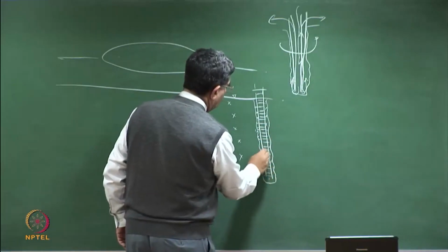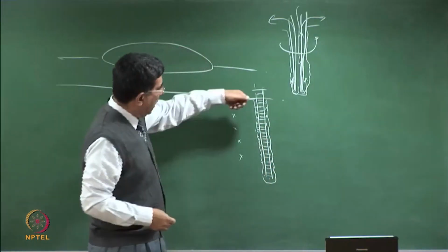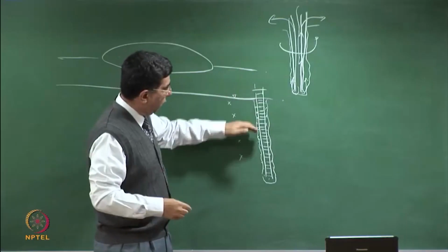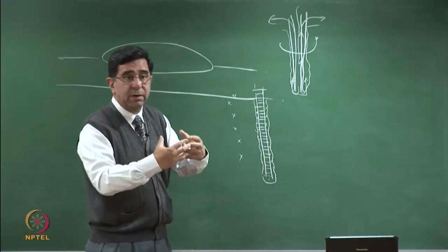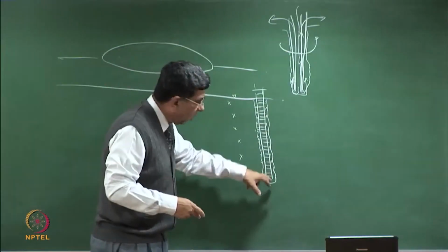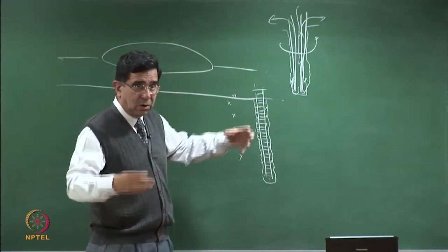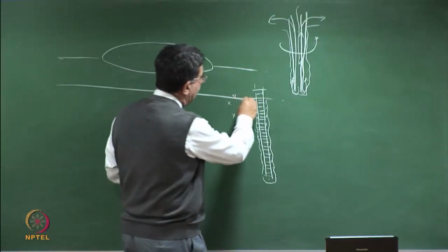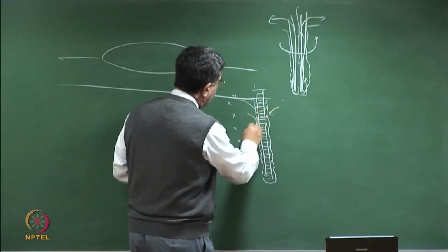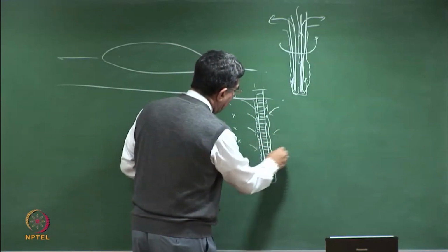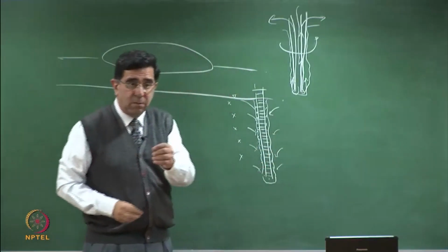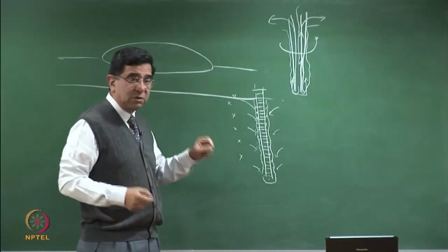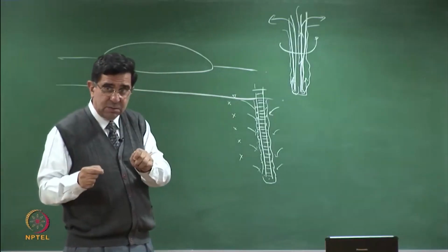So, anything you do to take out the water from here, the level will go down. I have to purge 3 to 5 casing volumes, more water will come in. That water will be mixed water of all this, because the water will flow like that. So, I am not able to pick up the water from 5 specific points which represents the original condition.